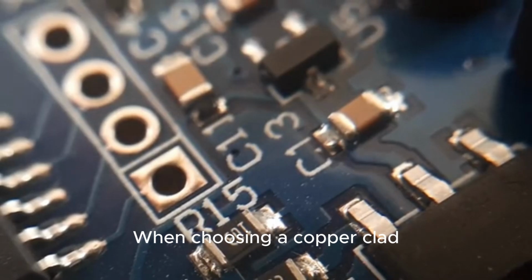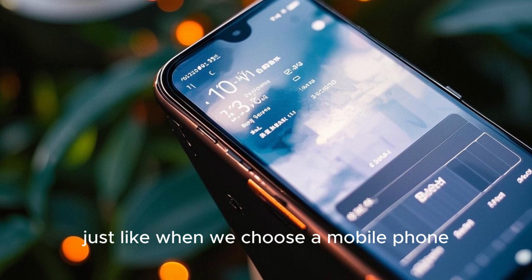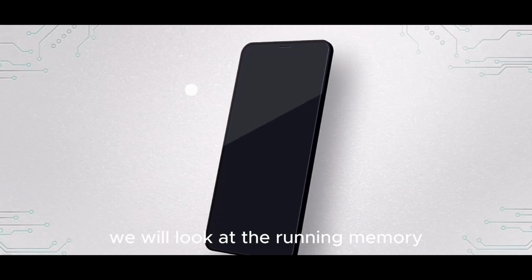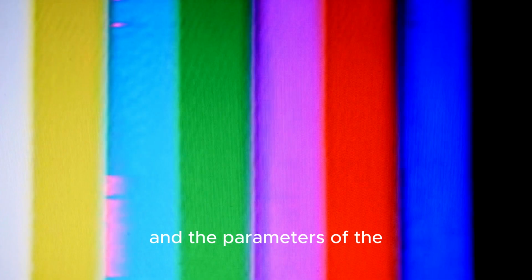When choosing a copper-clad plate of different materials, just like when we choose a mobile phone, we look at the running memory, flash memory, CPU speed, etc. And the parameters of the copper-clad plate are the glass transition temperature Tg, dielectric constant, and thermal expansion coefficient.